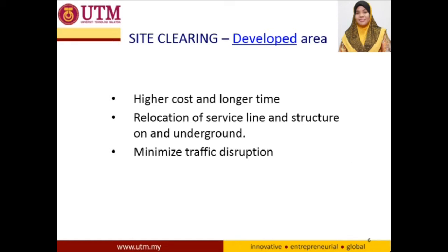Another challenging issue is to minimize the traffic disruption by providing a detour or alternative route with proper signage to ensure the safety of traffic flow during construction. There are some cases where traffic control may also be required to improve the safety of the road user.